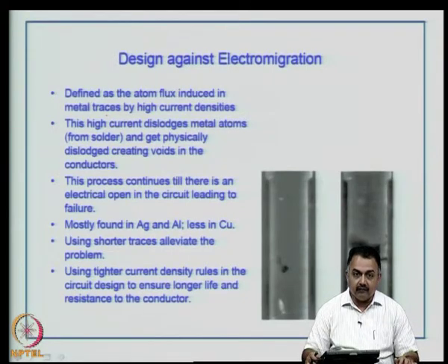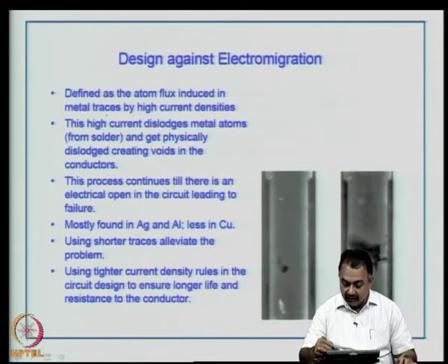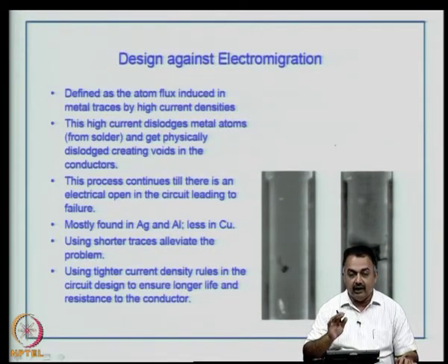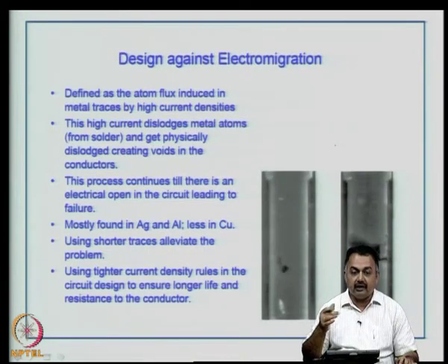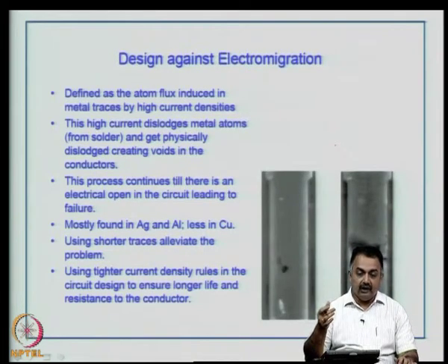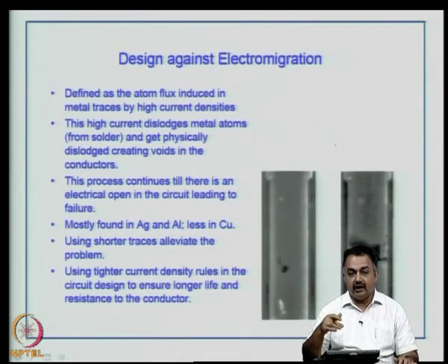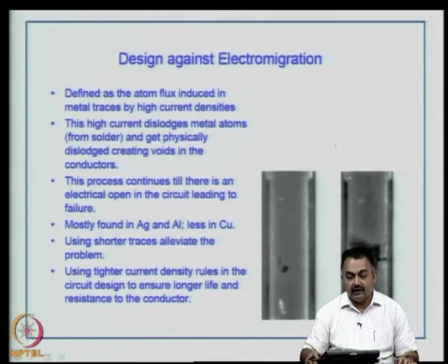The important thing which I want to mention is electromigration, especially if you look at tracks and the spacing between tracks, and if you have not protected them well, you can expect a lot of migration, depending on the different current densities that you are using and the kind of moisture levels, the kind of external debris and process debris if they are there.